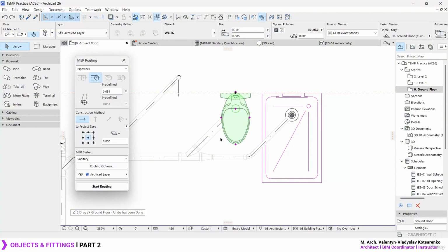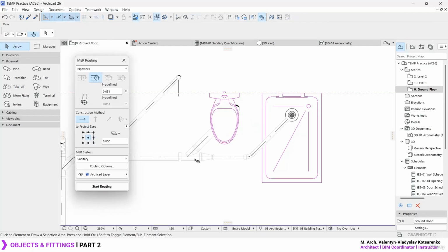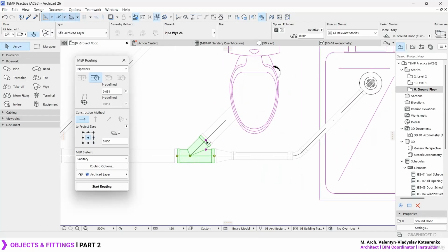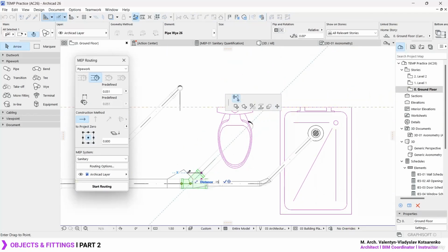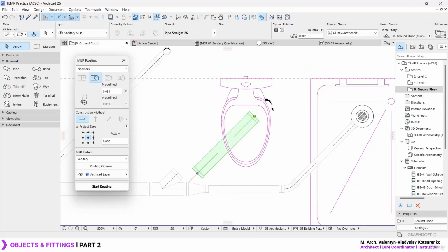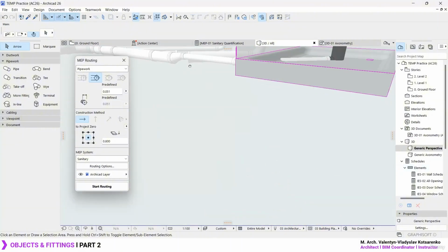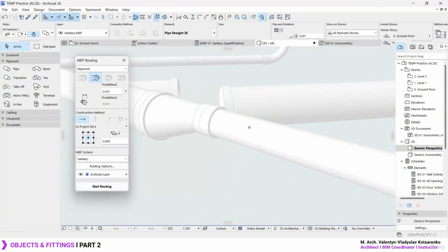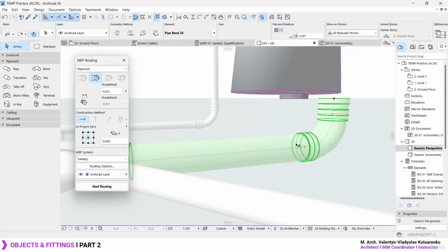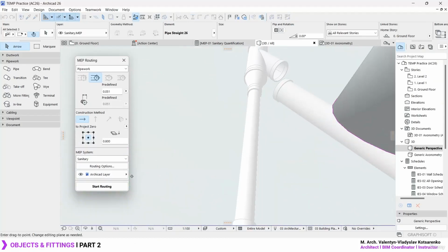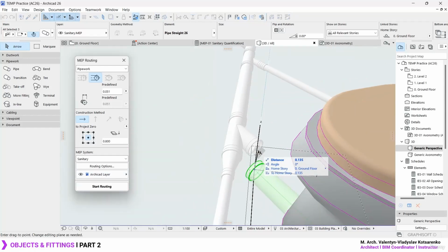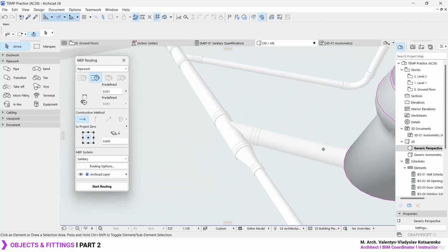If you want to adjust this, maybe let's say 15 centimeters to the left, don't forget you can select the Y feeding and activate the move inline command. Point 15 over here. It's going to adjust most of the branch, but you also need to select this branch over here and make sure that everything stays connected. So how about we maybe select this one, and this one, connect this to the Y feeding. Okay, right over here, make sure that it stays connected. And there we have it.